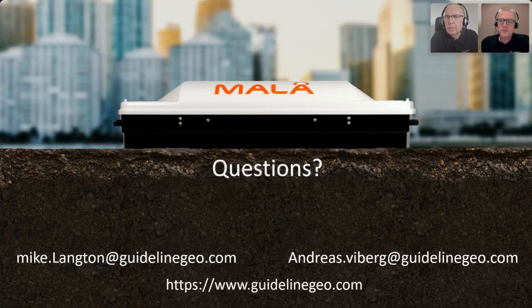Any others outstanding, Andreas? Some questions on how to integrate MIRA with GPS or robotic total stations. Yeah, most of the systems that output an NMEA string can be connected to the system. If you're going for a total station, that would output a pseudo NMEA string, but for most major brands it's possible to output that through a cable, and that is possible to integrate with the system, as well as on the GPS side.